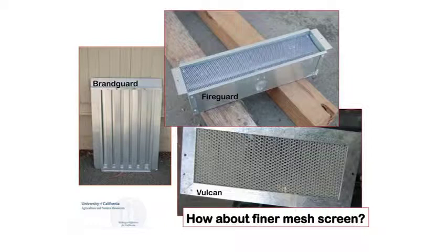So both of these have been accepted for use in the state of California, meaning that they've done some testing at a state-certified commercial fire lab, and the testing that they have done has been deemed acceptable for the time being. There isn't an approved standard way to evaluate these vents yet for ember and flame intrusion. That's being worked on now. But until that standard has been approved, the state has accepted them for use temporarily.